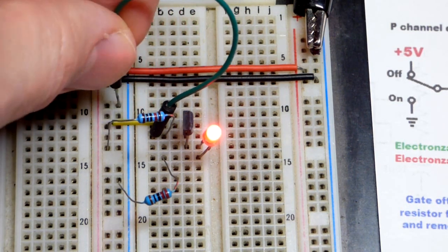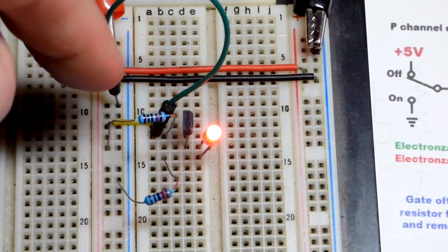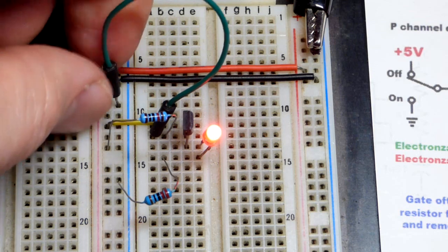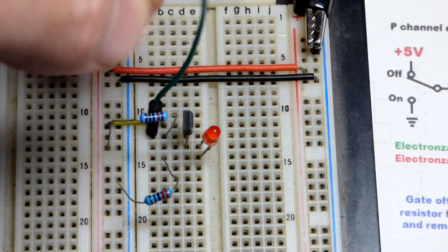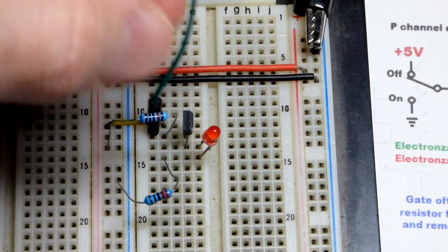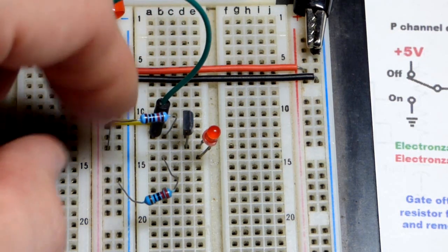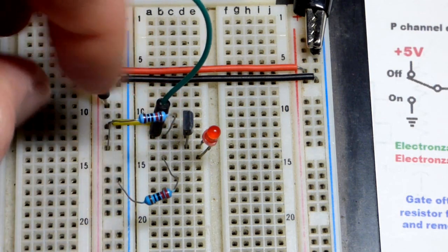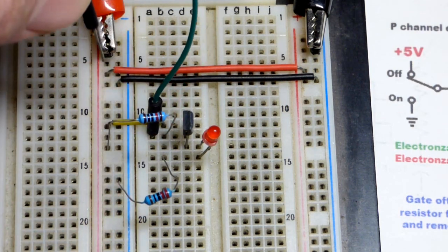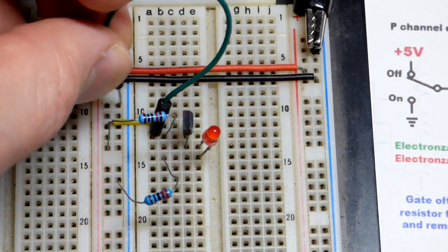That's a direct connection right there. Doesn't matter right now that we have the resistor. There's a little bit of current being wasted through the resistor. But when I yank this, it's going to be off. It's going to stay off. My body can't get stray signals. Of course, we can put it to off there. So the pull down resistor will also work if your input is either off or to the negative supply. You know, you could do that as well.